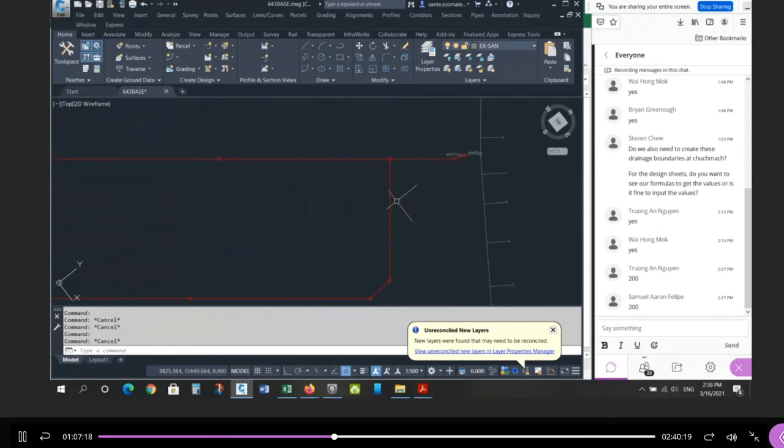Okay, now the numbering system for this, I'm going to show you. This is how I would number it. What they're doing in this subdivision is backwards to what I taught you in CDA. Okay, I want you to do what I taught you in CDA. I want you to start at the bottom at the outlet and work your way upstream by increasing the maintenance hole numbers. So I'm just going to draw this here off to the side so I can discuss it. Let me just get the sketch ready. One here, and then there's the existing pipe. Sorry, I'm just redrawing it so I can discuss it.